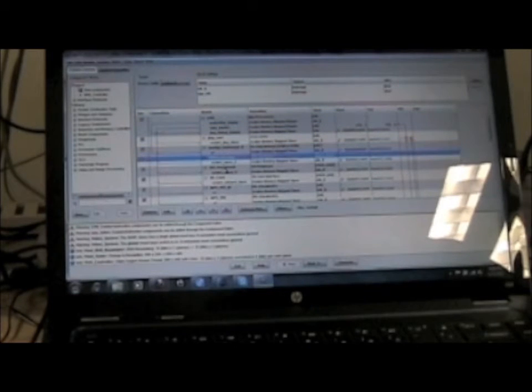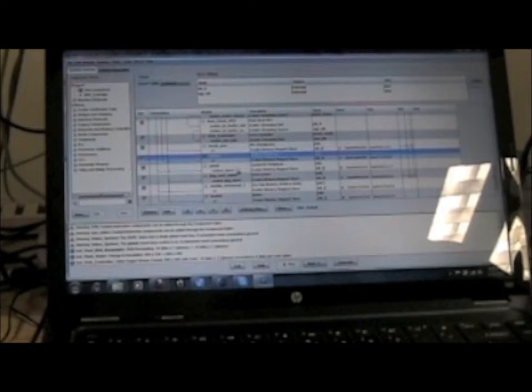As you can see here, this is the audio processor. It's connected to on-chip memory, has an I2C controller to configure the codec, an SPI peripheral to talk to the MP3 decoder, and the SD card where it pulls the data from, and has parallel ports to communicate with the decoder. Then there's the video processor, which has a pixel buffer, DMA, and a whole bunch of other peripherals that make it work. A lot of the LCD controller functionality was pulled from reusable, off-the-shelf IP blocks. It connects to SDRAM, and then there's another on-chip memory that is shared between both processors that allows communication to happen between them. And that is it. That's basically the interconnect system of the processors and their peripherals.